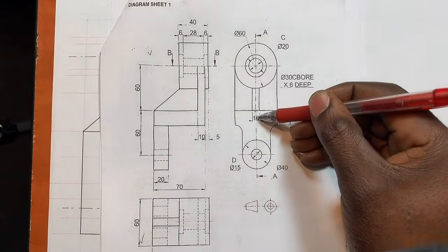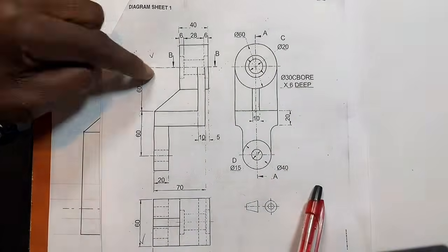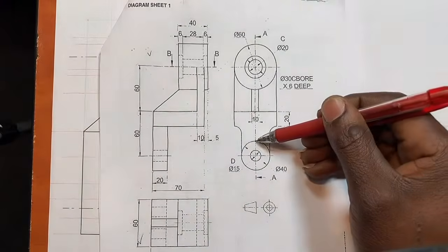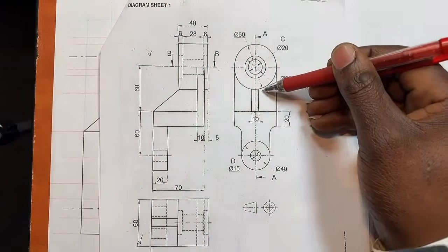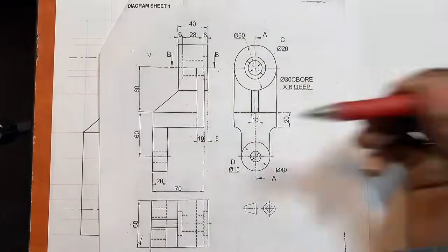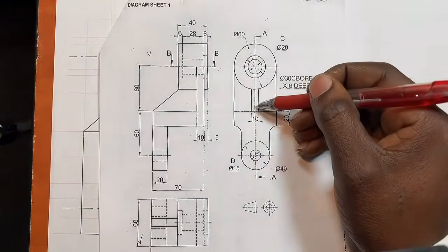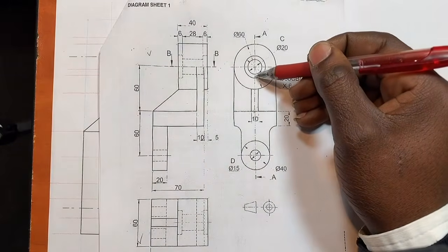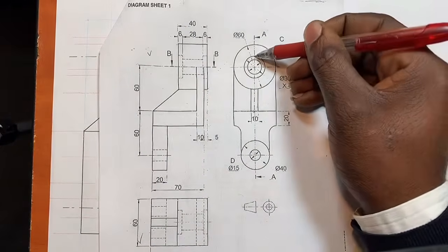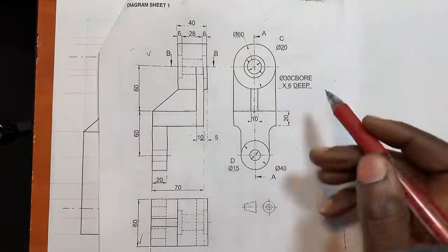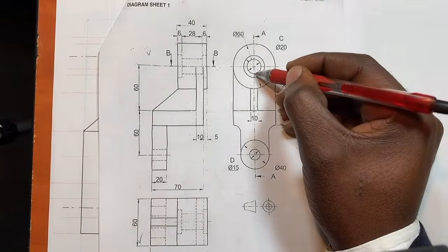Do you see that I'm actually tracing it on my left view? What if I want to section the front? You understand? It will go, and go, and go. It's going to come across the supporter. However, it's still cutting it along its height. You understand? Go, go, go. From here till there is going to be a hole that is 6 millimeter deep, isn't it? But when you get inside, there is another hole of diameter 20.